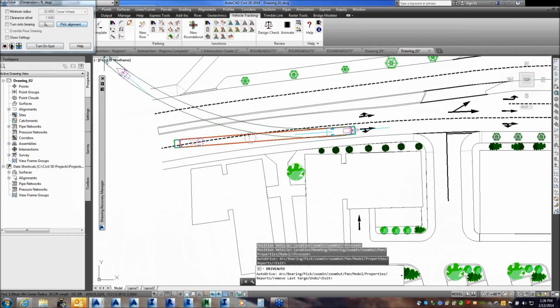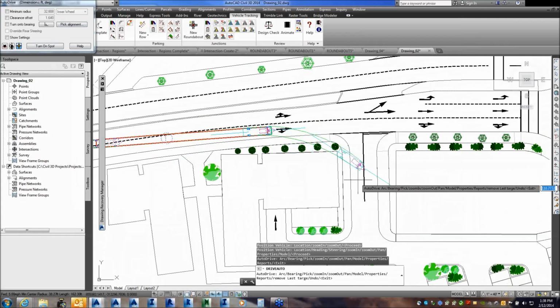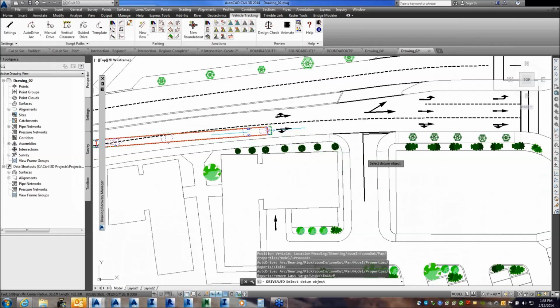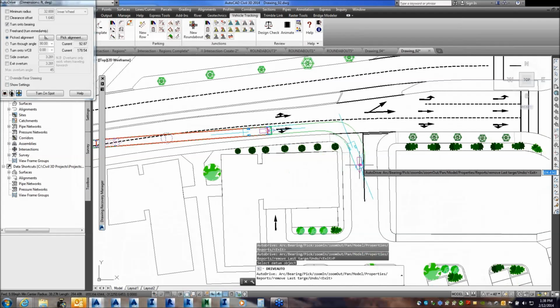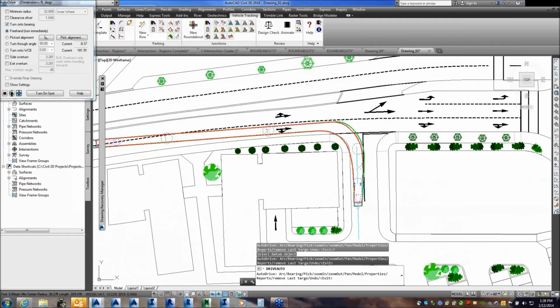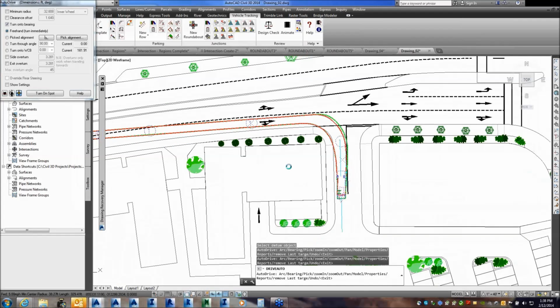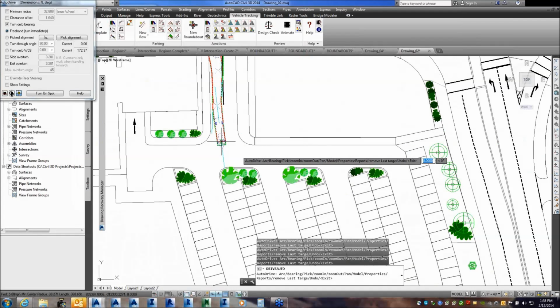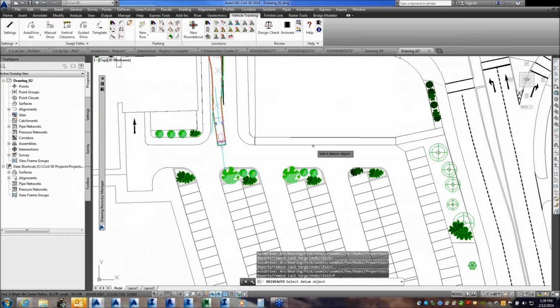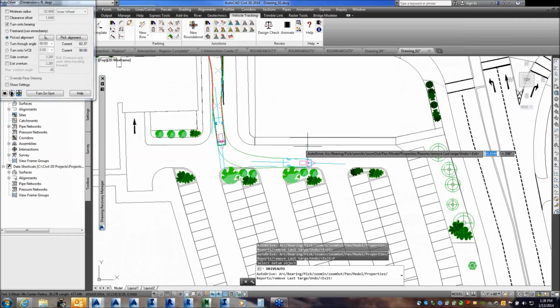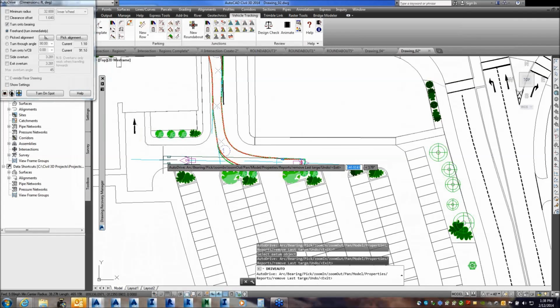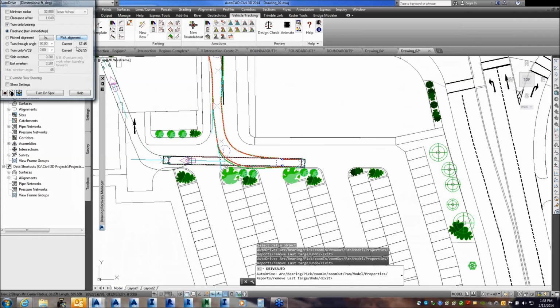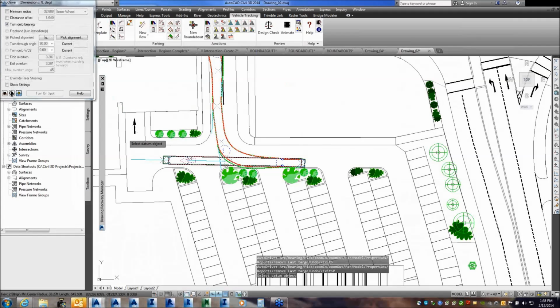When I want to see if a truck will actually fit in there, I'll use this as an alignment for my turn point. Then I can pick points coming in, pick the alignment here for my turn point, and then come straight back and pick this alignment to turn back into this dolly.